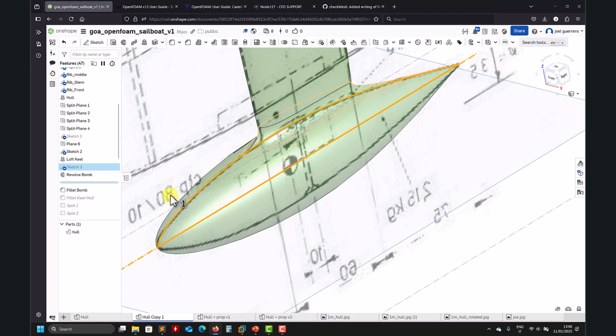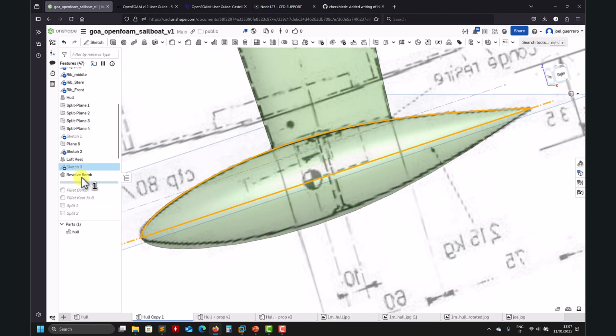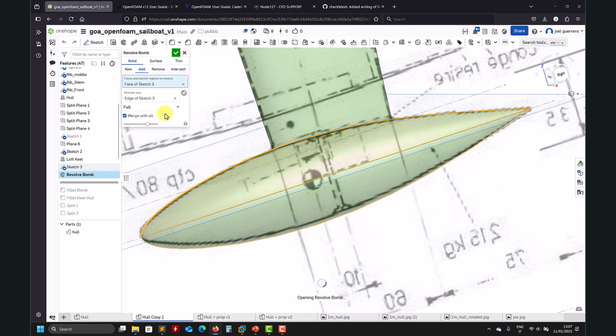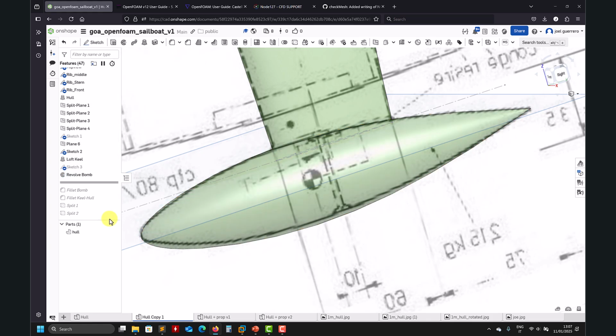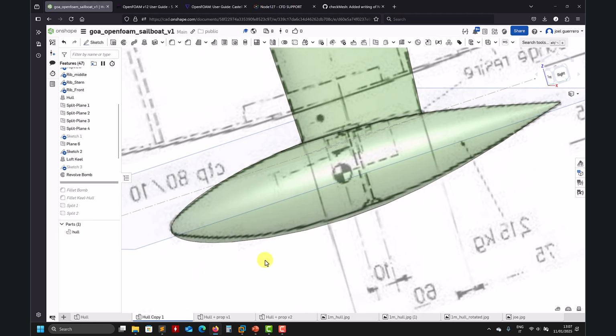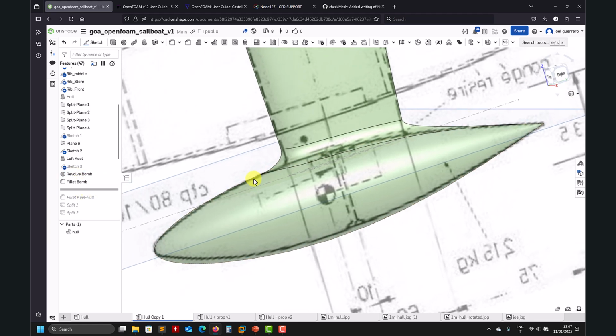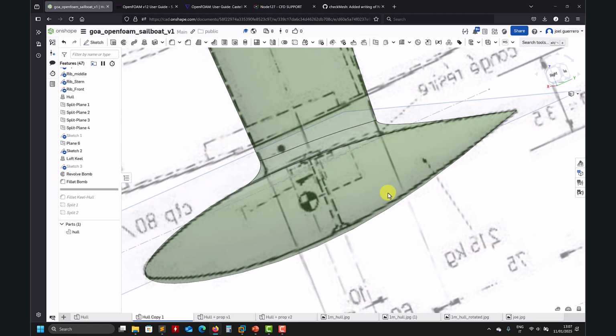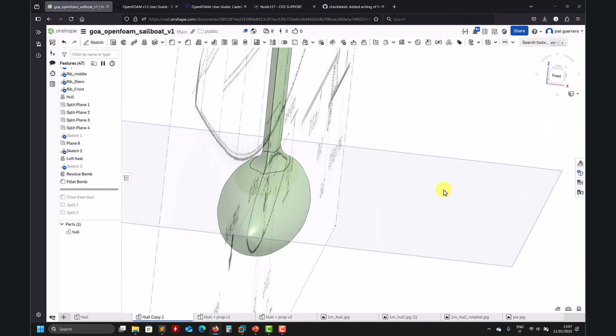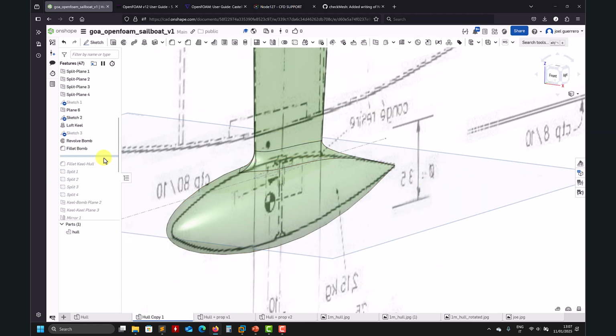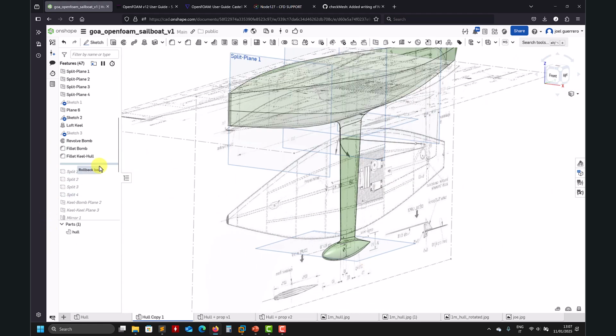Okay, so let me go here. So there you go, revolve, and each of these operations, look at that, I'm doing add, merging everything automatically. You can do it individually, new part, and then you do the Boolean, you have the Boolean operations here. So now we have this fillet, you add a fillet there, fantastic. So now look at that, it is very similar to our sketch. Then more fillets and so on. I don't recall, then you follow, but these are the steps here.